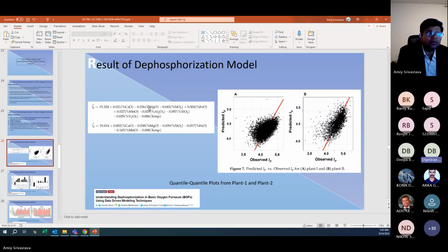31 ppm in your BOF is not that bad, I would say. I think this is not bad. But whenever we process these heats, the nitrogen pickup gets higher. When this heat is cast into a slab, nitrogen crosses 40-50 ppm, which is bad for the interstitial free grade.